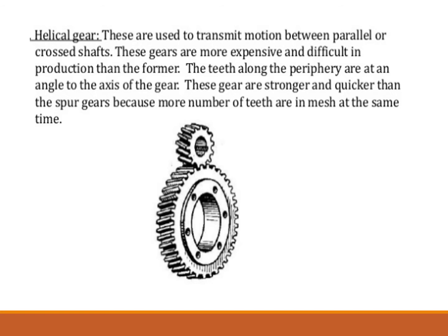However, in helical gears, the friction, heat generated and wear are high because of the sliding action of one tooth on another. Therefore, helical gears should run in an oil bath, as in automobile transmission. Another disadvantage with helical gearing is that helical gears exert an end thrust which must be absorbed by a thrust bearing.